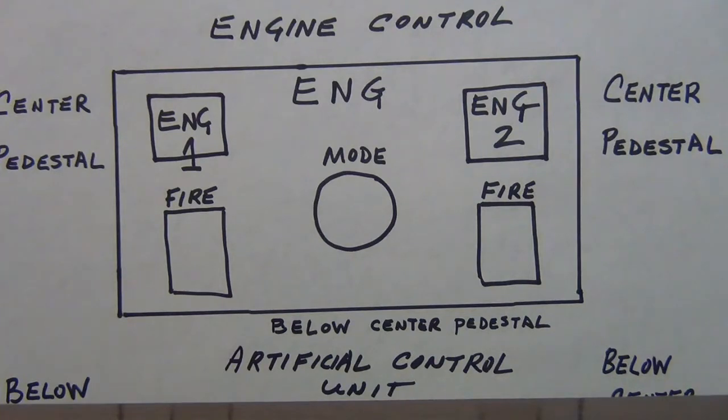Okay. Also, the FADEC basically gives instruction. Your FADEC, again, just to reiterate, is your full authority digital electronic control unit. It's always there preventing the engine from exceeding RPM limits. And if some of you are interested in a little bit more detail about the physics between your engine RPM and also your EGT, because exhaust gas temperature limits are extremely important to a pilot.